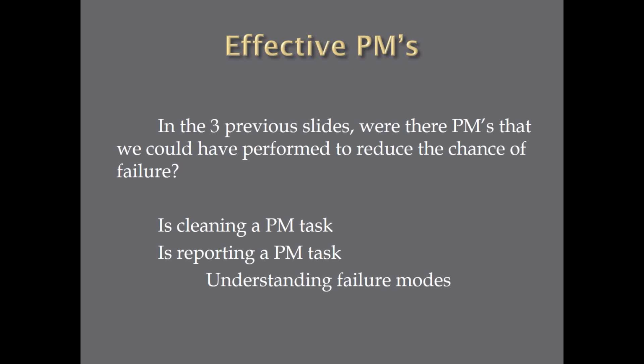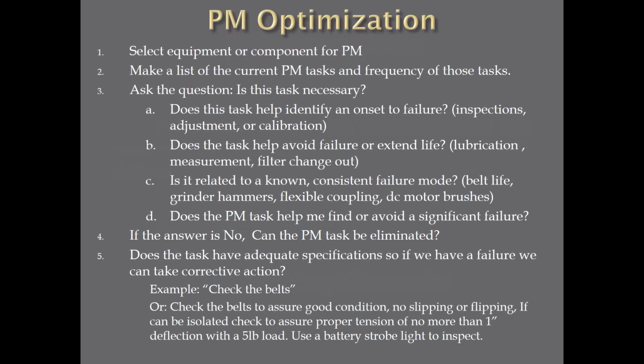Now, operators in this case were union. They weren't allowed to do PMs, so we called it operator care task. These inspections were operator care tasks. We were finding failures because they understood how the equipment components can fail. Very good process. So here's my PM optimization form.